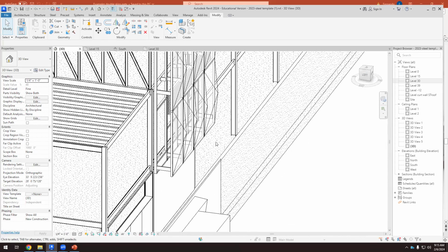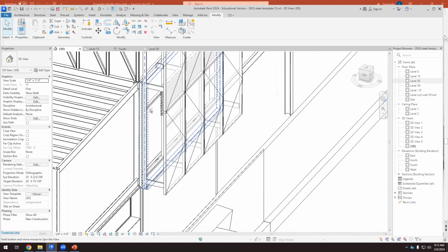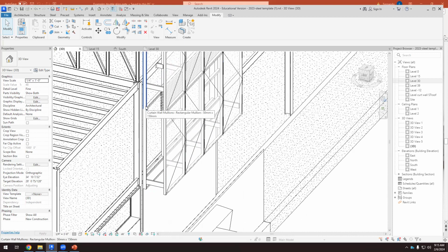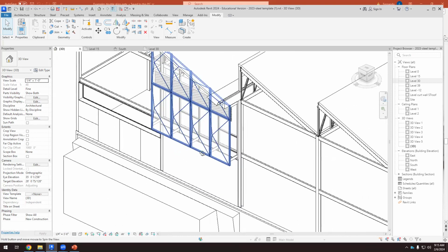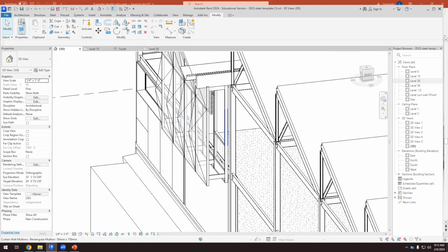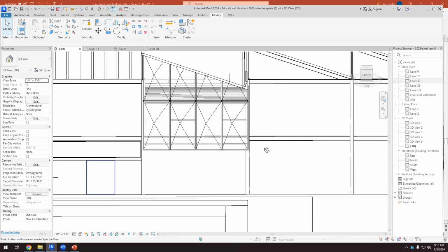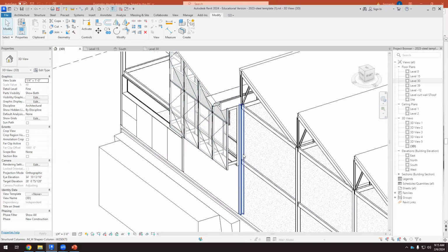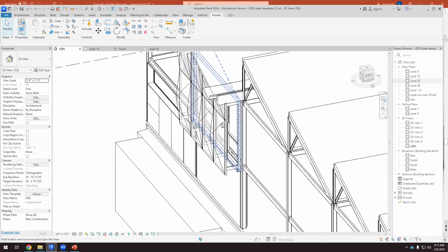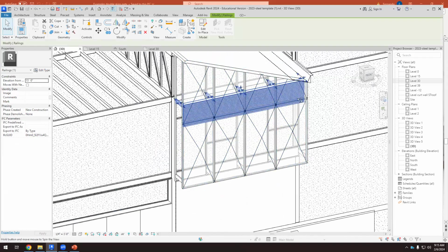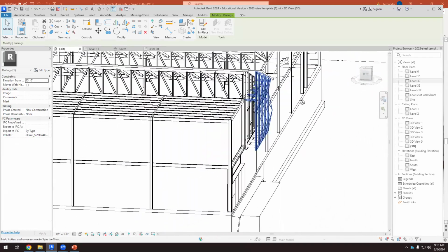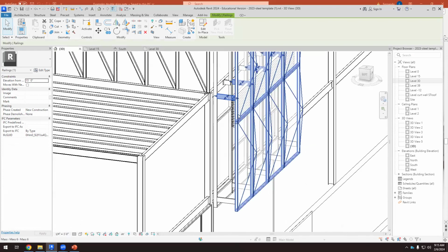So we are adding details to this. Okay, so it's not just a curtain wall. We don't use the ready curtain wall option. No, we are first designing a curtain wall with the right partitions. Then we are designing a double skin, and there should be a relationship between the first and the second skins, at least with the vertical mullions, so that I can easily connect them.